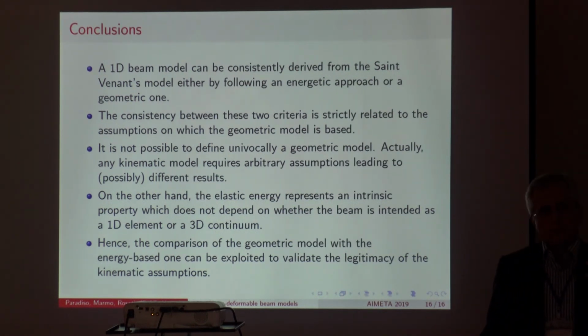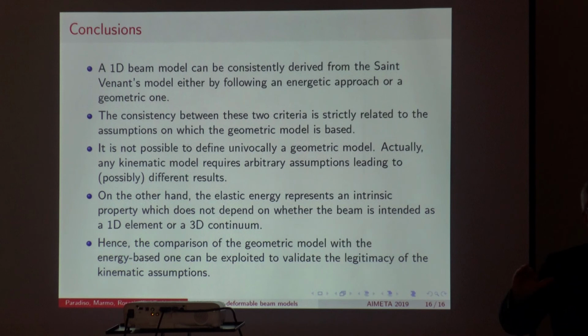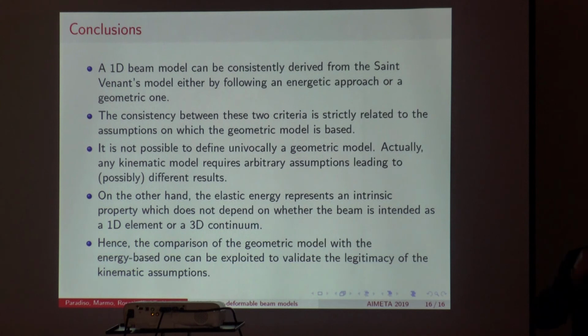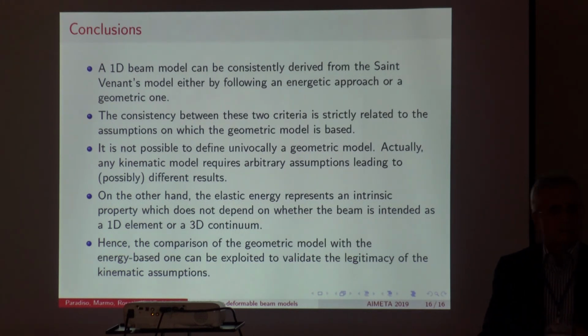This source of confusion becomes greater when you read the literature, in which you always find confusion between the definition and the use of the terms center of shear and center of torsion. To make things even more confusing, when you have a thin-walled section, the two points tend to coincide, or when the Poisson ratio is 0.